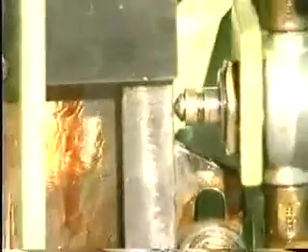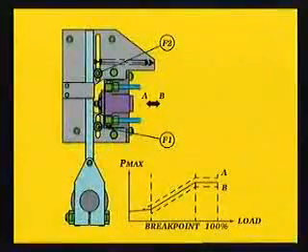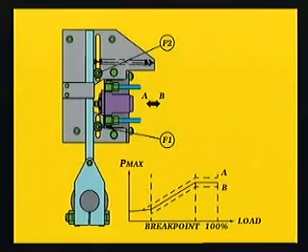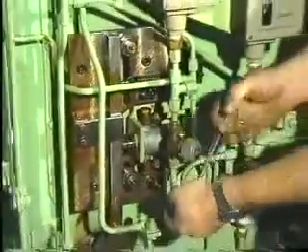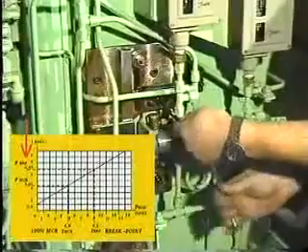Steel rod touches both pivoting points. Displace the pilot valve bracket until the calculated control air pressure at breakpoint is obtained.